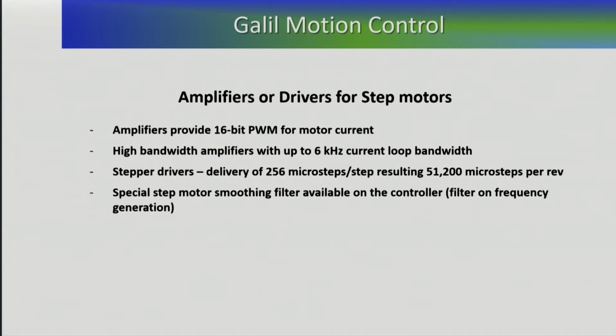Amplifiers come into play. And amplifiers, the torque ripple, in many times when you're working with the higher resolution systems and you're getting into micron, submicron systems, the torque ripple can contribute to the disturbances. And those can be addressed by looking at the amplifier and saying, can I use a linear amplifier so I have the highest resolution and I avoid torque ripple?